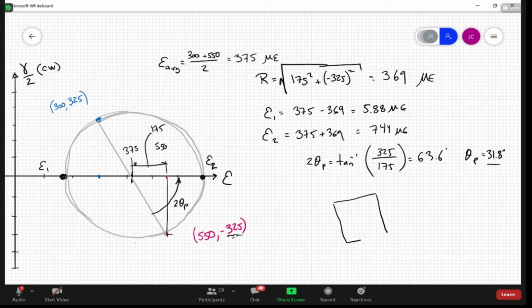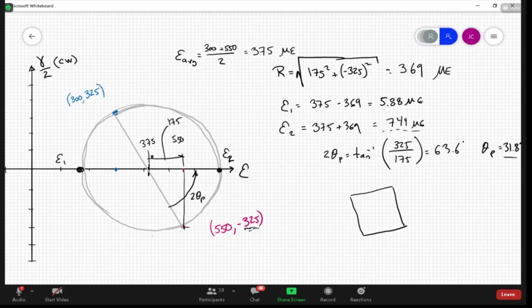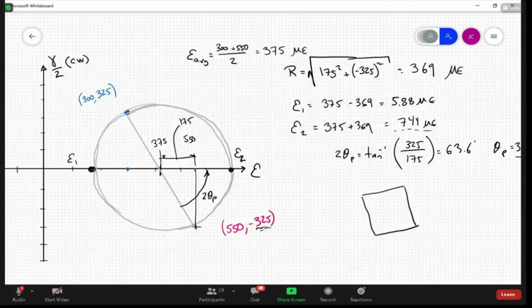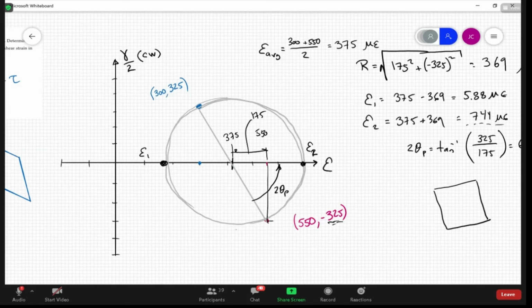It's maybe a little less than 30 degrees. Thirty degrees would be a little bit more than that, but whatever. Let's say that that's it. So in that case, we have two normal strains, no shear strain, so it's going to stay rectangular. Most of the strain is going to be on the epsilon 2 face. So this was the purple face right down here, which is this top face. So the top face corresponds to this, and that rotates 31 degrees into this orientation.